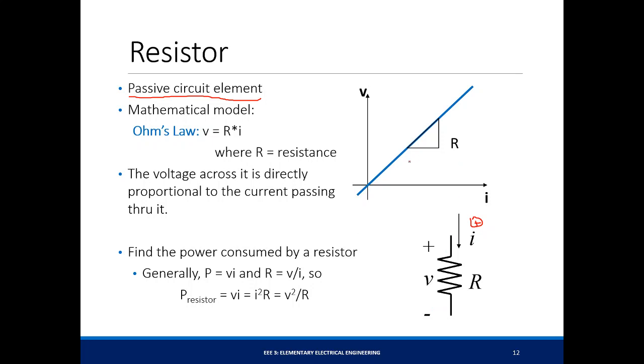And to get the voltage with respect to the current passing through, there's actually a linear relationship between them across a resistor. This is the VI curve of your resistance or your resistor, and that is defined by Ohm's law actually. So if you have a VI curve, the slope of the line between your voltage and current is R, as you can see here.